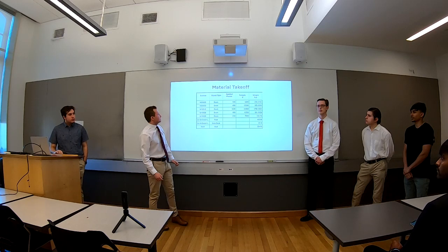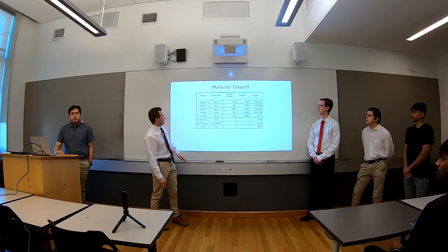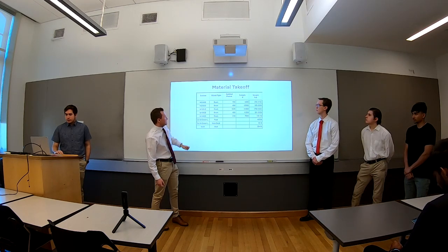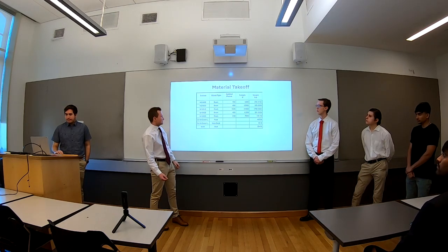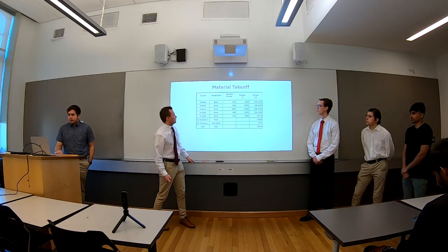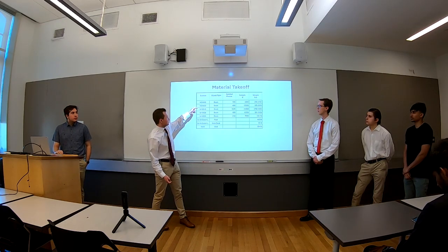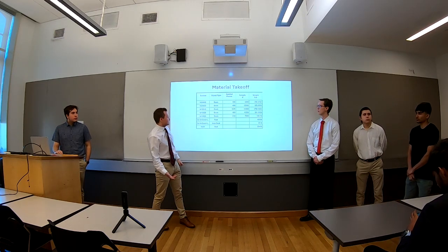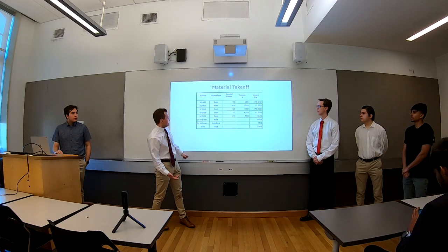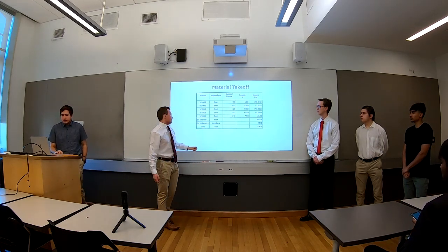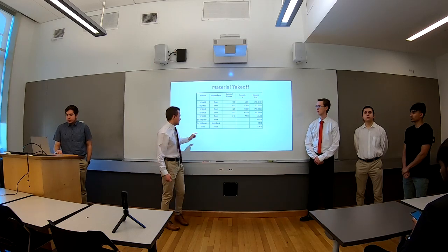So now we have the material takeoff. This is for all 40 floors. As you can see, the majority of the beams are the W18 by 40, which is over 1,000. We have W21 by 50 beams for a length of 12,000 feet. The 18 by 40s are 44,000 feet. These other beams aren't used as much, but it's still a lot. We also have the weight of all of the metal decks and concrete decks and the weight of the walls.